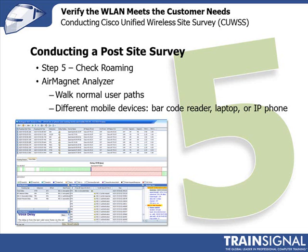And it collects information about when the roaming is taking place, the channel parameters that actually triggered the handoff between one access point and another, and gives you a quality assessment as to whether that roaming experience was good or not so good. Based on that information, you can then decide whether you need to change something in the configuration, maybe alter the power level of the access point, restrict certain data rates, etc.